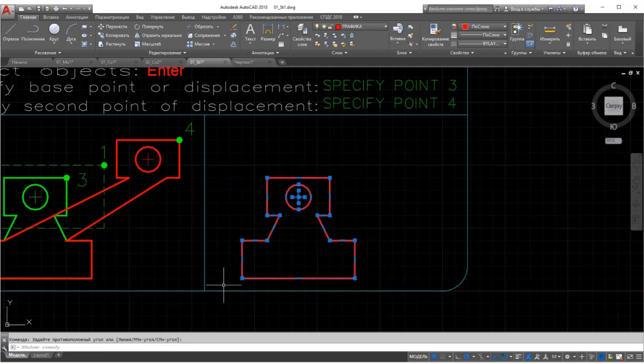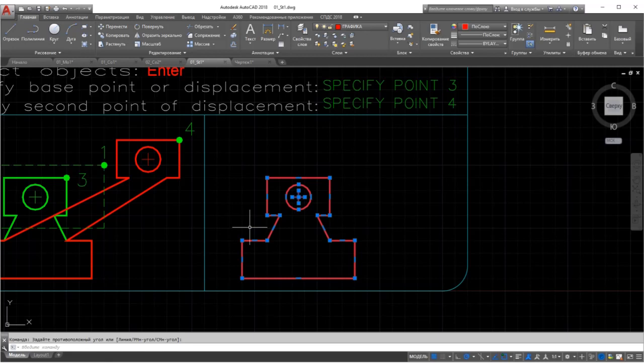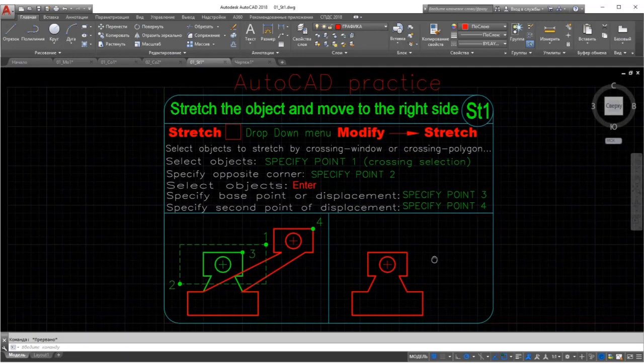If you edit with the method of preference set to selection first, AutoCAD gives you the option of dragging a polygonal window or crossing area, or simply dragging a series of lines through the objects you want to select. You simply click a point and drag to the left or right to get rectangular selection boxes as described above, or you can choose the W polygon, C polygon, or fence option by typing the appropriate letter at the command line.